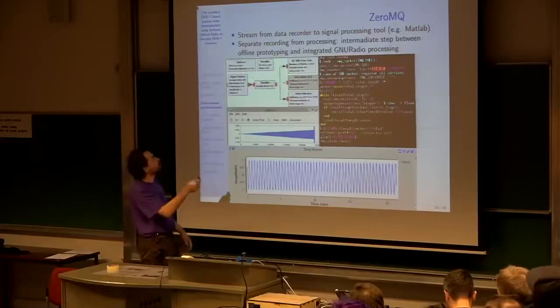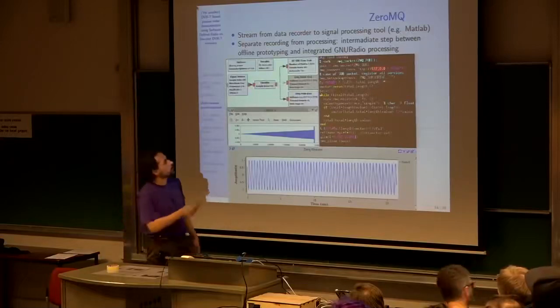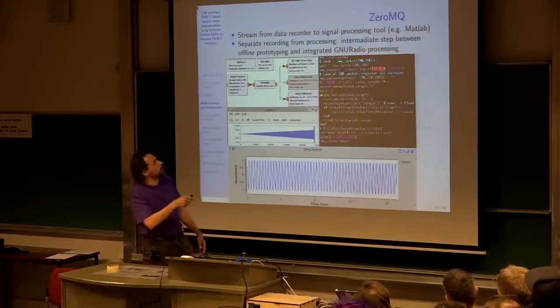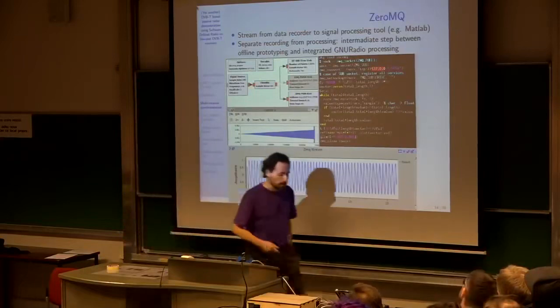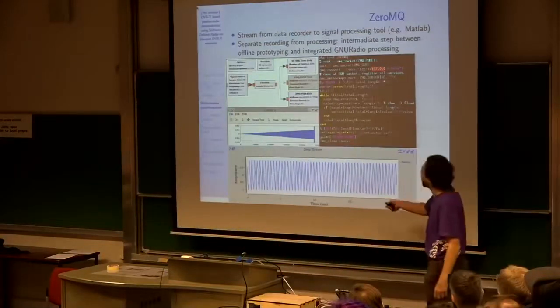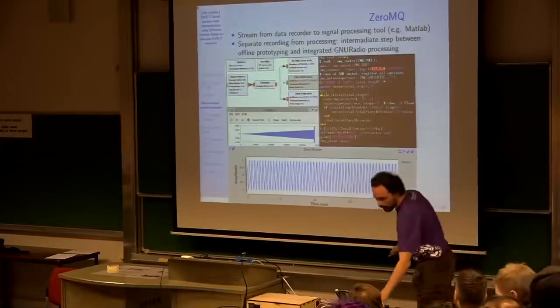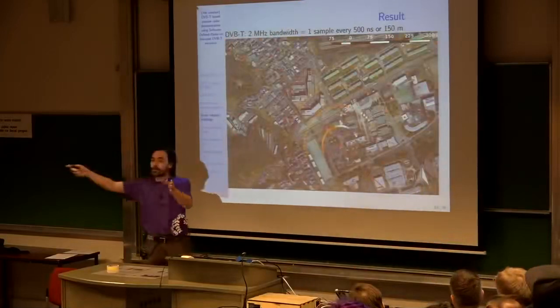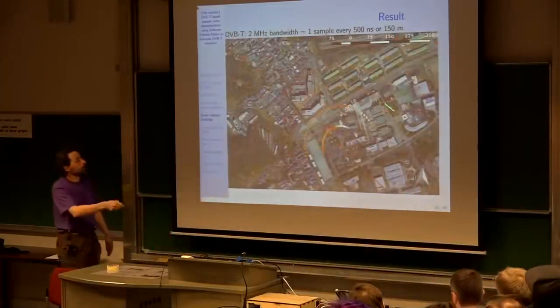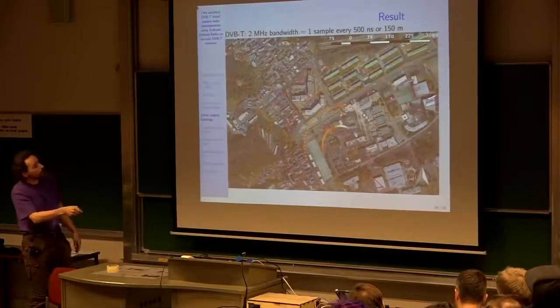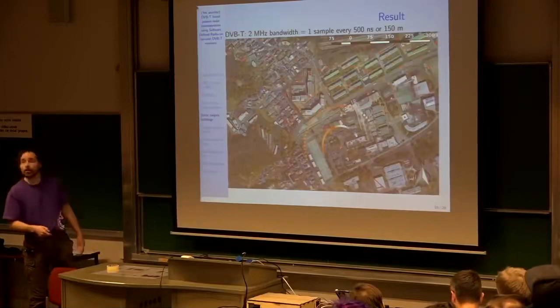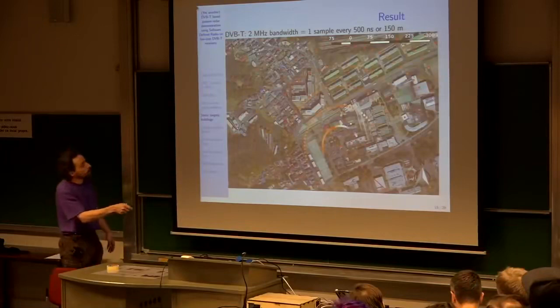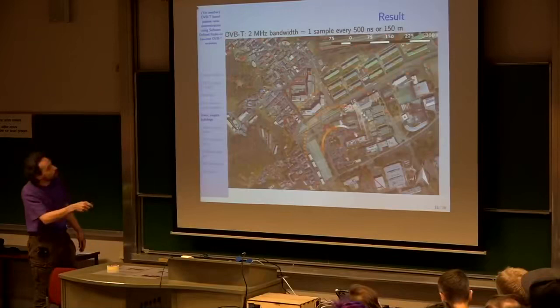So that's a demonstration: GNU Radio streaming data through a UDP 0MQ sink, and GNU Radio collecting the data for a source. So it's working pretty well. This is with synthetic data. And when you do this with real data, and you take your reference antenna and rotate it in azimuth, so you want to look at different areas, well, you see here, each one of these dots is a correlation peak. And we do see the nearby building giving more reflections. And if you trust me here, there's a bit more energy on this large building here.